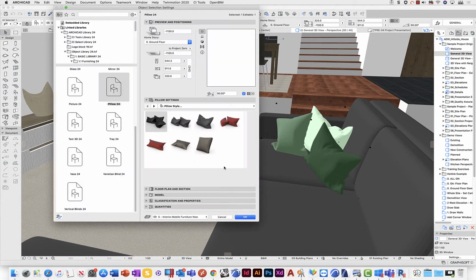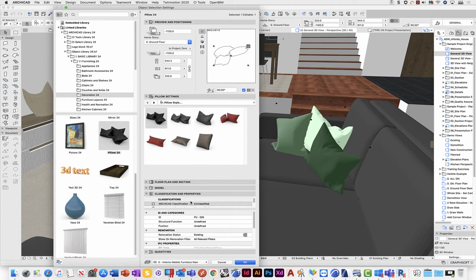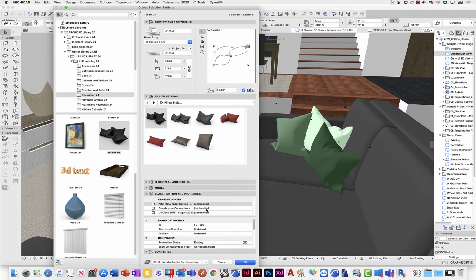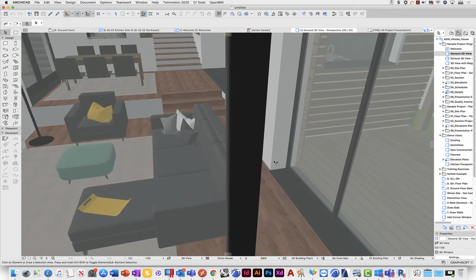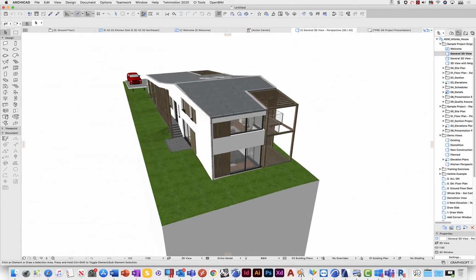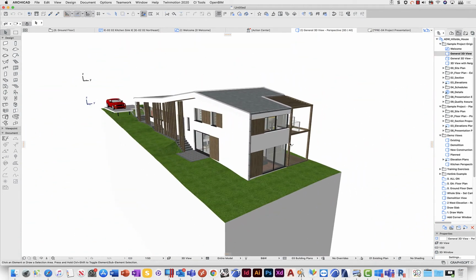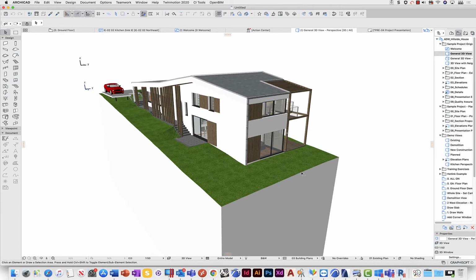So look at this. The classification of this element is unclassified. That's fine because elements that are not classified are left as building element proxies, which may as well be this thing as an object. A piece of furniture, it doesn't really matter. Half the time that stuff can be filtered out. That's a little bit too much detail to go into, so why don't we just kick on and go through the process of saving out an IFC.